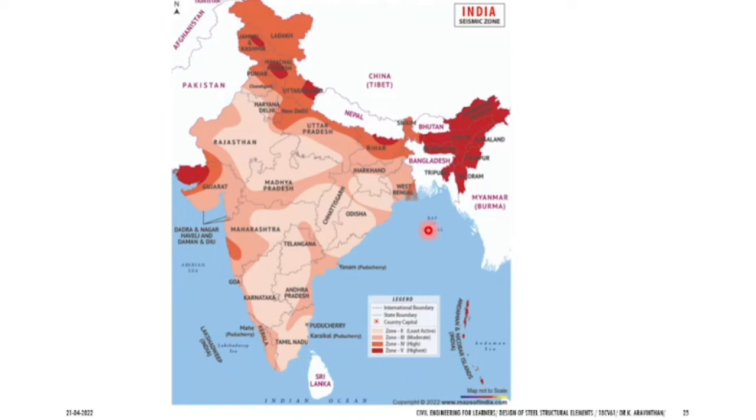But in your career, you might go through length and breadth of the country. Some days you can go to Himachal Pradesh due to certain work, or else in Rajasthan you can work. When you are going to those parts of the country, if you are a project engineer or site engineer, definitely you have to consider certain things. If you are there and working on the Gujarat part of the area, which code book is required? IS 1893. If you are constructing more than 12 meter height, which is very much essential.